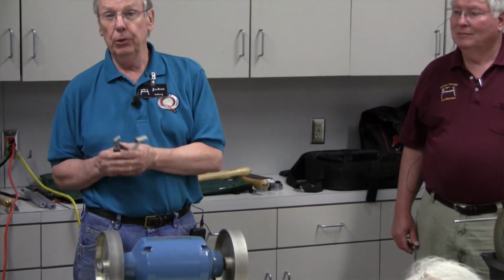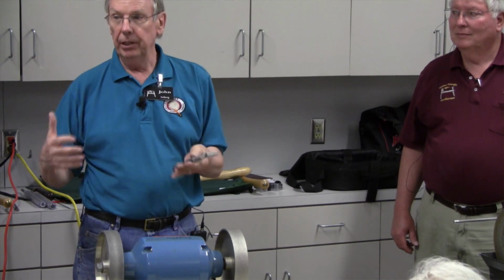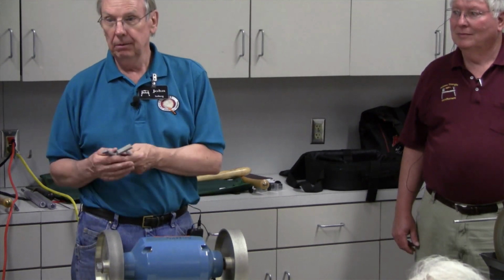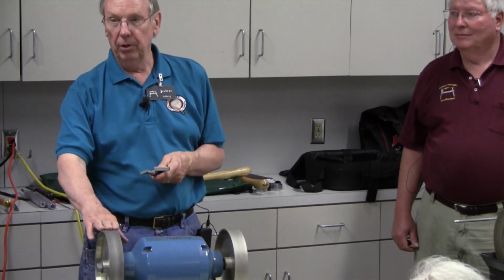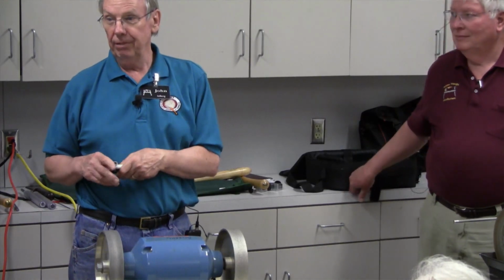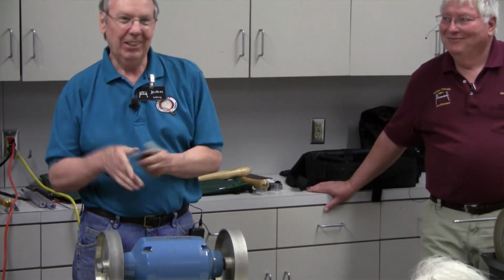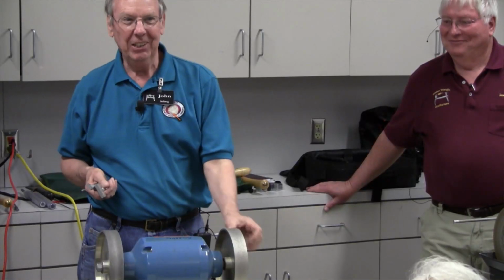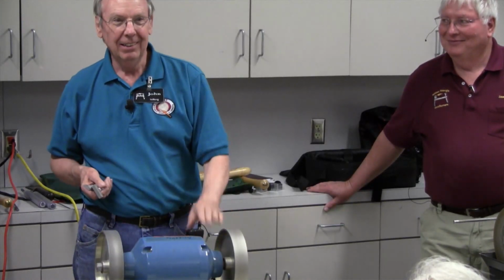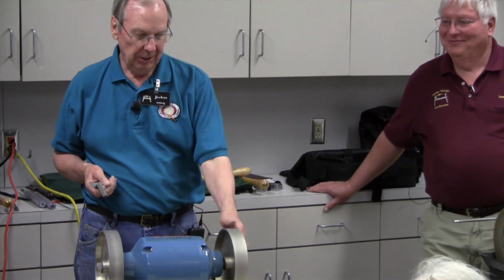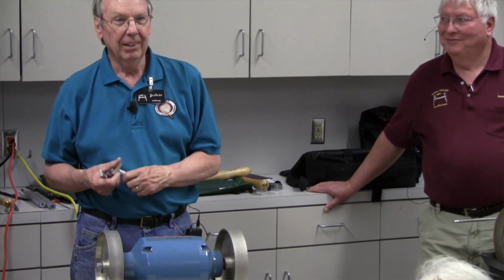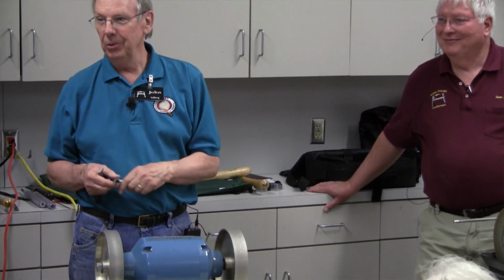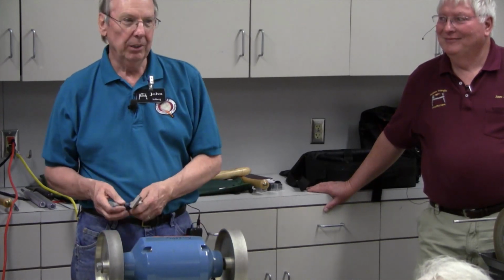And one of the processes of doing that is that over time your wheel's going to get smaller and smaller, and at some point you'll need to replace them. The last time I replaced mine before I bought these, I had them under 6 inches. They were like 5.5 inches. And I was getting such terrible concave surfaces that I said, I've got to replace these wheels. So that was one of the reasons I ended up buying these CBN wheels. I had to replace them anyway. And I had to spend the money for a couple of aluminum oxide wheels. I said, I'll spend the money for a couple of good CBN wheels instead.